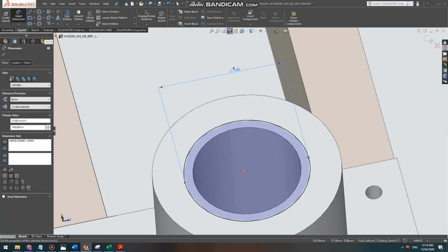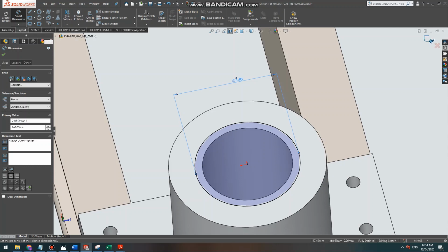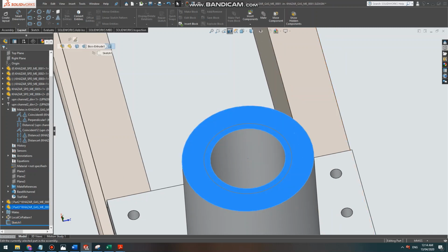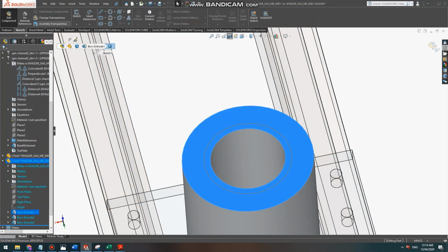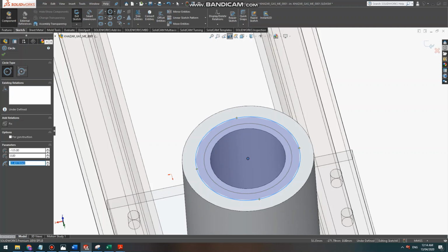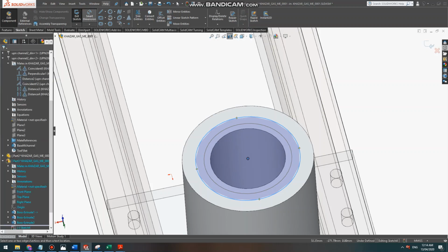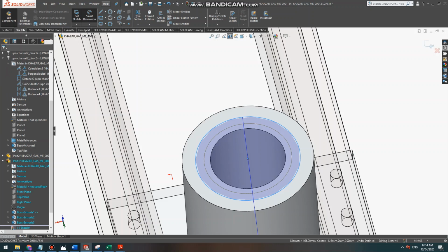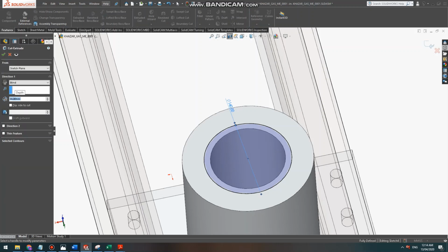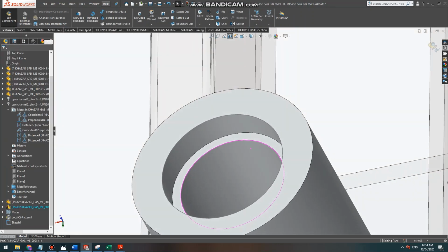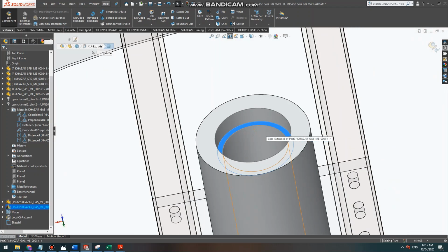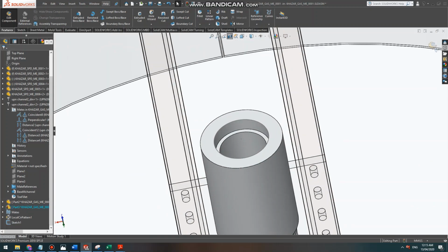We have drawn it. Now wait a minute, it's not a part sketch, we have to make it a part sketch. Then we have to do the sketch on it, 140. So we make the drawings 140. We extrude it by 34 millimeters. That's the place where the bearing will sit. You should put radiuses here as well, but we'll do it later on.